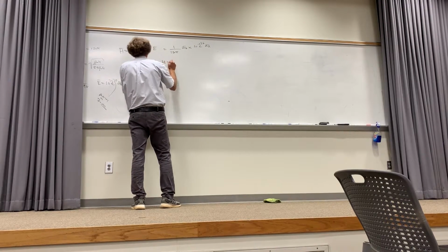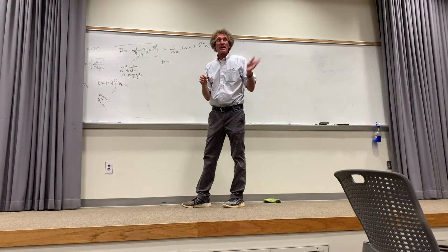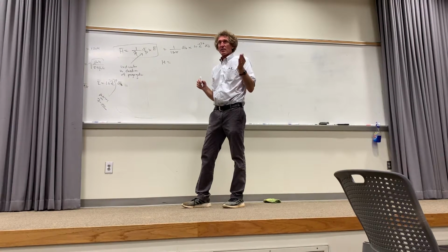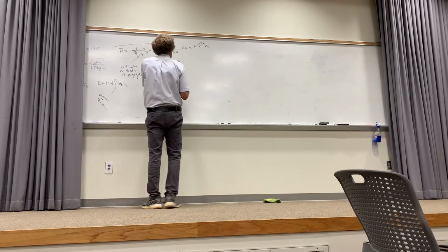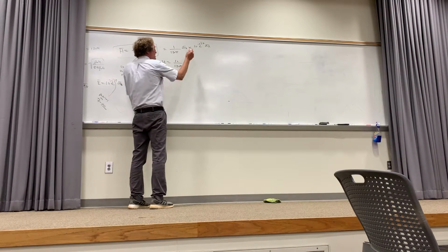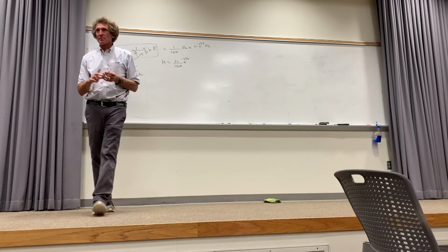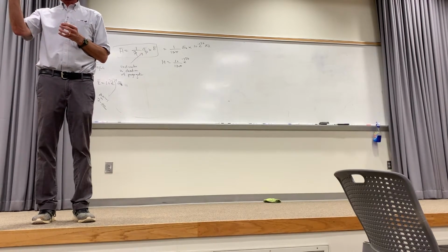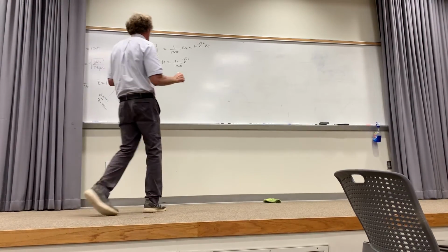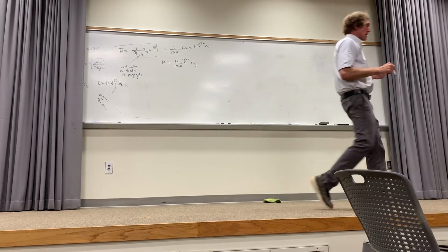That means H, notice I'm using this equation. This is a very important one. It's an easy way to get H from E for propagating electromagnetic fields. This is not for steady state E fields or H fields. Follow me? This is propagating, and I'll make a comment about that in a second. So if I look at this, what does it come down to? It's really a magnitude of 10 over 120 pi, times e to the minus j3z. And what is z cross x? Y'all remember that? It's x, y, z, right? If you start at z, you're crossing x, you get y, don't you, class? So it would be in the a_y direction, and that would be the H field you get. All right? Using a simple thing.